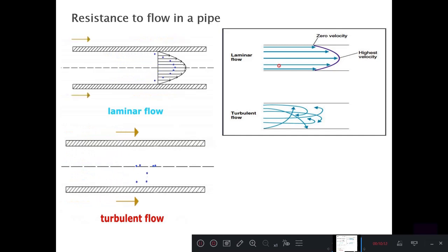So this movement of fluid elements relative to each other is associated with a pressure drop called frictional losses. Pipes with smooth walls such as glass, copper, brass and polyethylene have only a small effect on the frictional resistance. Pipes with less smooth walls such as concrete, cast iron and steel will create large eddy currents which will sometimes have a significant effect on the frictional resistance.